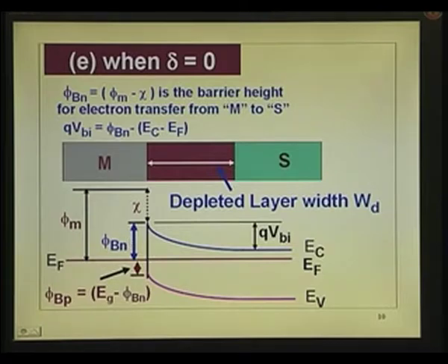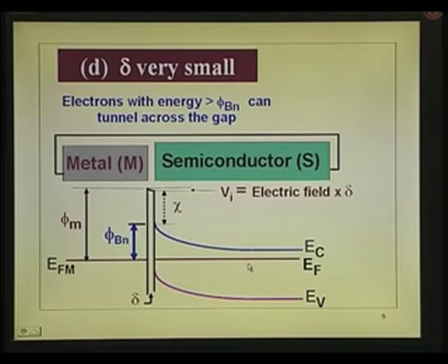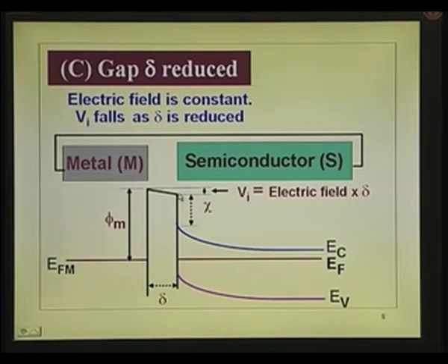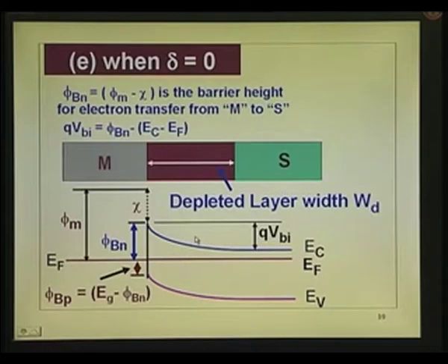That is the diagram. Now, if you remove the metal contact, also there is no problem. So, now you can see the vacuum level phi m. The conduction band is there, chi up to the vacuum level, and what else? Phi s is from here to that point. But just one thing I want to point out here, I have not drawn the vacuum level on this side. How will the vacuum level be on that side? See, we have not shown, even here I have not shown the vacuum level at that point. So, the vacuum level will show wherever the potential change is there, it will follow the same path. So, I just draw that for completeness sake.